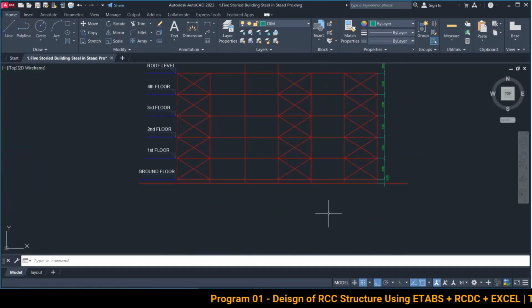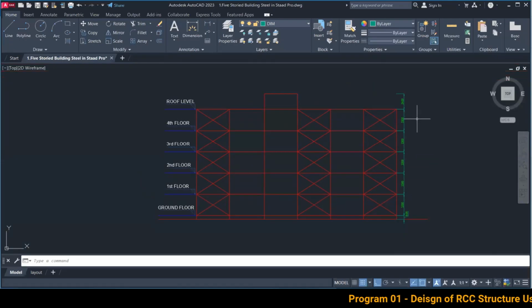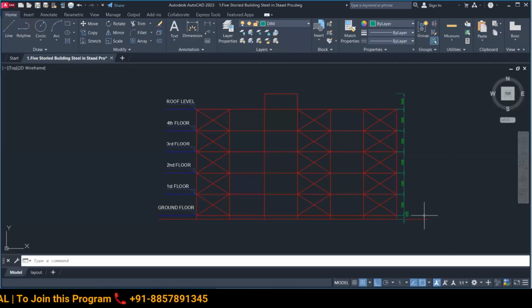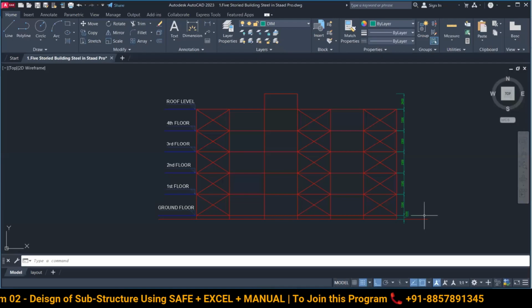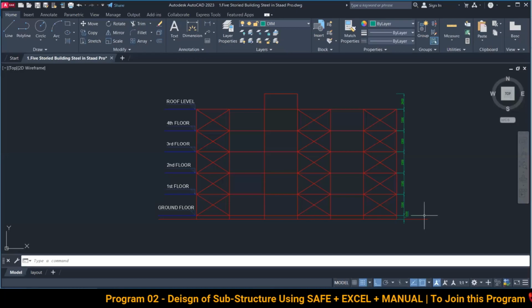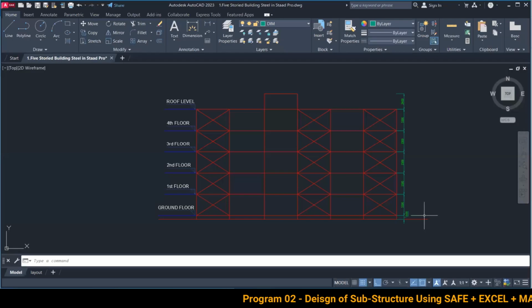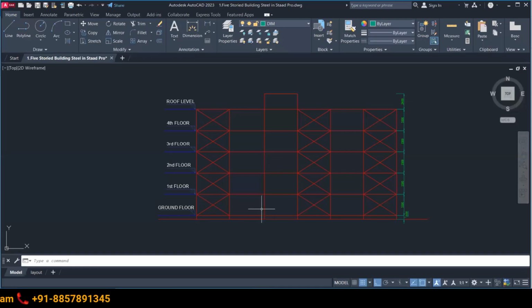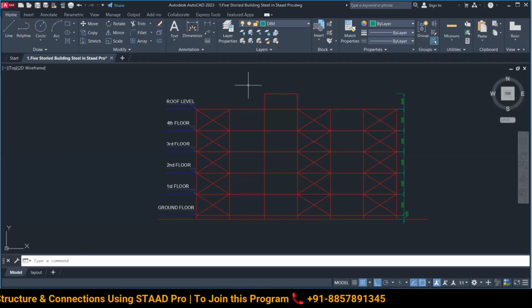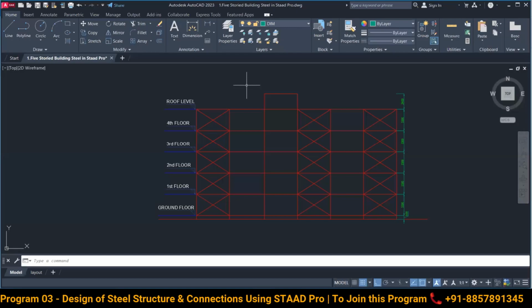The next thing that is important to us as a structural engineer is the elevation of the building. Here you can see we have a rough elevation. We have a 600 plinth level, and above the plinth the ground floor starts. We have a floor to floor height of 3 meters, and we have almost 5 floors up to roof level, and then we have this headroom which is 2.4 meters in height. And this is the location of the bracings, the vertical bracings. So this is the basic information which we need from the architectural drawing.